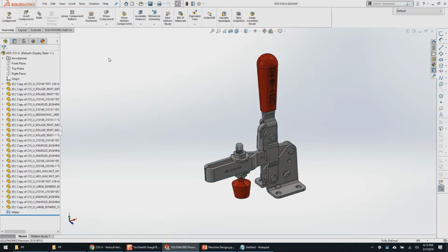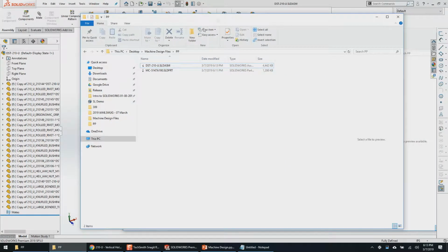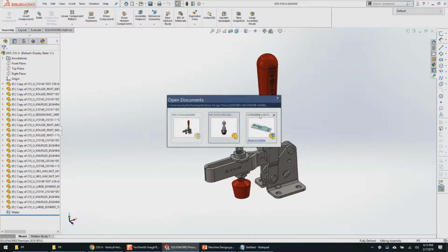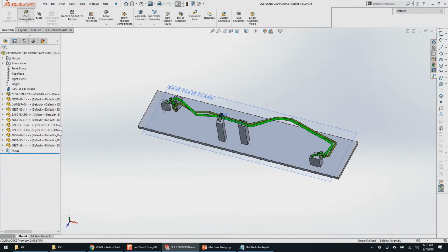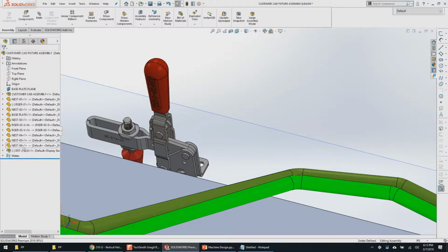So now let's make them virtual. What virtual will allow me to do is embed all of the subcomponents inside of the assembly file. You can only make parts and assemblies virtual inside of other assemblies. So now when I hit save, I can go to my purchase parts directory. I can download my original Parasolid file, and I can delete all of the parts that I downloaded. So I now have a single part file, which is my McMaster bumper, which I may or may not need, and then a single file, which is a SOLIDWORKS assembly that has subcomponents embedded inside of it.